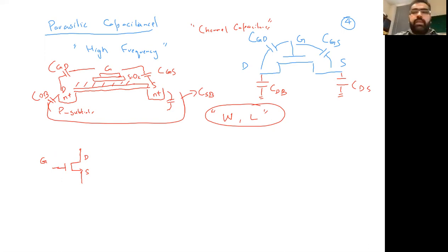Make sure recording. Yeah. So between a gate and drain, there is one capacitance, commonly known as CGD. Between gate and source, there is one capacitance, commonly known as CGS. Between the drain and the body, because the body is grounded, we can say in case of NMOS, CDB. In case of PMOS, it's VDD, but still an AC ground. And since I didn't say the source is grounded, I can say source and bulk also we are going to have. So these capacitances, all of these capacitances, we need to bring in